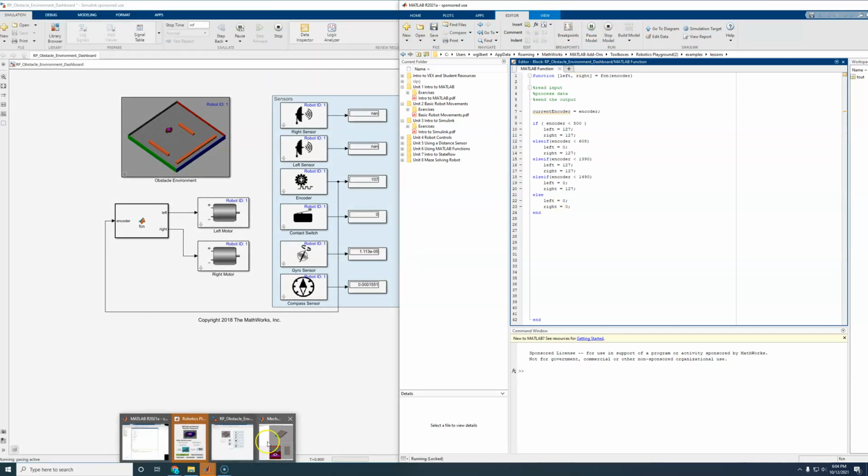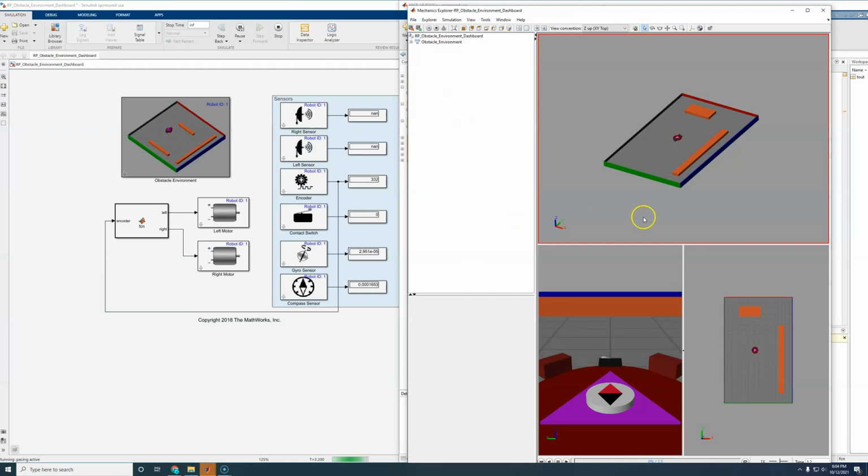Again, do the math. Don't do what I'm doing, which is troubleshooting when you'll spend too much time, but do the math. Use your wheel ticks. You know how many ticks there are per revolution. It's in the documentation for the game. You know how big the wheels are, so do the math.